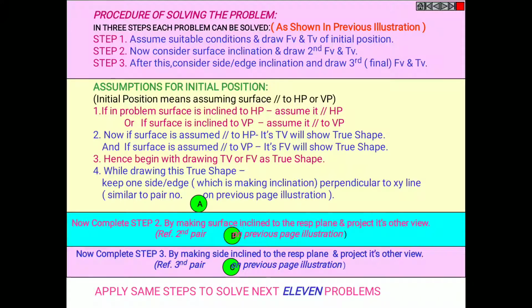Step 2, now consider surface inclination and draw second front view and top view. Step 3, after this, consider side or edge inclination and draw third final front view and top view.